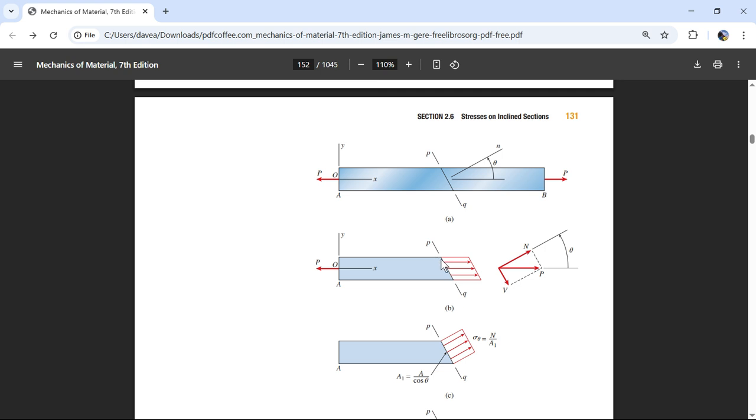So you might be like, whoa, it's for sure going to rip apart, right? Well, the area that it's acting on is at a 45-degree angle, so we get more area. But this being 70% and this being 140% more area, those two basically, like the square root of 2s, drop out, and you're left with half. And so the shear pressure is going to be 29,000 psi.